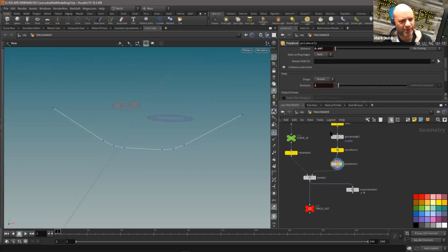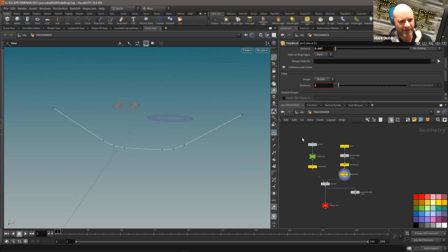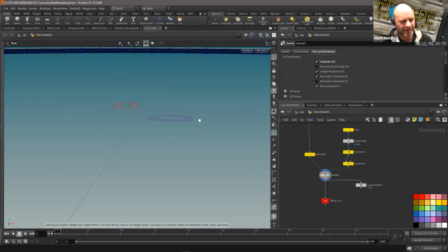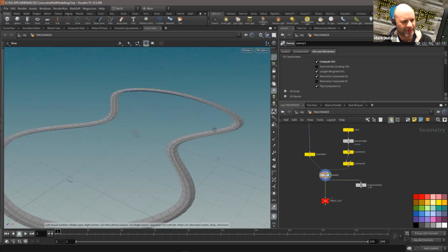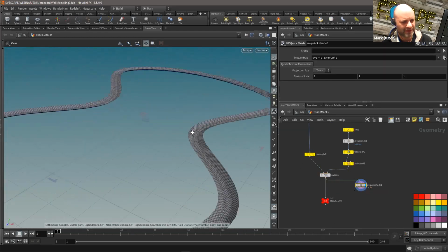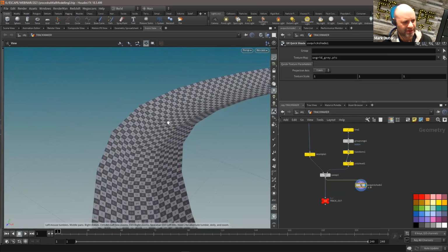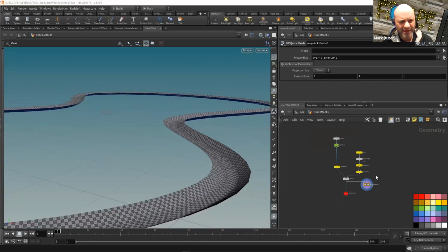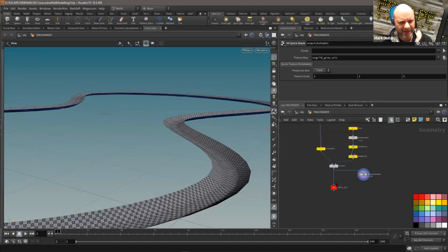Something like this, which just gives us a better cross section. Well, it just gives us some control. So again, the user might want to do that. So I'll mark those 3 things like that. Let's just move this up a little bit so we can see that the tool begins at that point. So again, if we sweep that all the way through, turn on the sweep node, have a look at it when it's UVs, you'll see the cross section is exactly how we'd like to model it. So that's pretty much it for this track section.